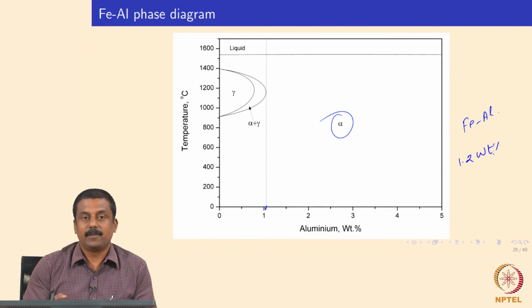So if you look at it now, there are complexities in microstructure development because of these alloying elements. We need to now understand the basics. Without understanding these basics, we cannot modify the weld thermal cycle. I just showed you two examples of the effect of alloying elements such as silicon and aluminum, which are very important to stabilize retained austenite. If you have these two alloying elements, you already see a tremendous change in the distribution of microstructure in the fusion boundary, in the fusion zone microstructure.